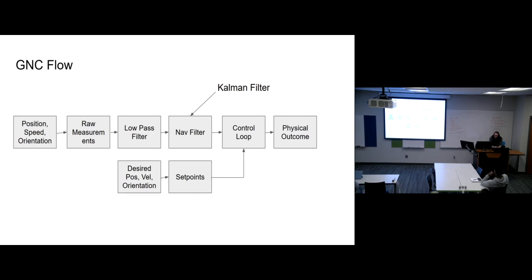We also had times where I wrote a piece of code that was supposed to sample from a sensor in real time at some arbitrary hertz, and then pipe it off to a different thread or process for dispatch into a control loop or into some metrics thing. And that was when I realized those actually need more concurrency, because if you just send things off at rate n and it gets there at the time latency of n+1, you find your control loop is no longer synchronized.